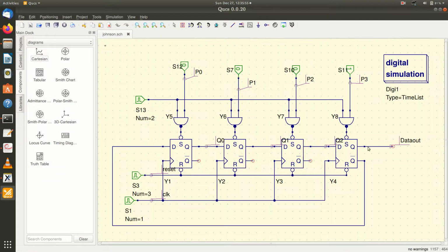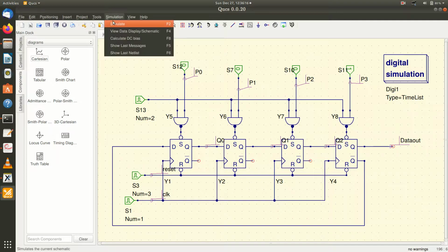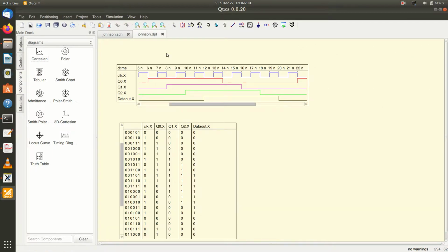Here you can see that instead of connecting the Q output, you connect the Q bar output of the last stage to the input. Then as usual, I feed it with 1000, some arbitrary pattern, applied in parallel through the preset inputs. So we will see this parallel in serial out operation, the operation of this twisted ring counter. With 4 flip-flops, it will count 8 clock cycles. Still, it is a very inefficient counter. You can see these waveforms here.